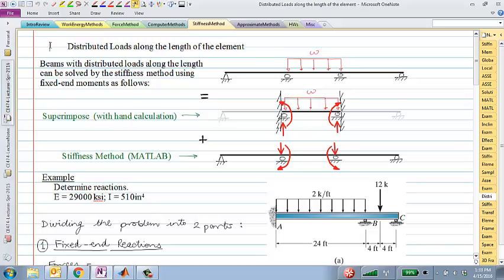And solving it by hand essentially means that you would have to go through the entire process, set up the element stiffness matrix for element 1, for element 2, assemble the global stiffness matrix, and then you would have a few different degrees of freedom that are free and specified. So I believe for the first problem there should be 4 degrees of freedom that are free, and for the second problem there should of course be 3.